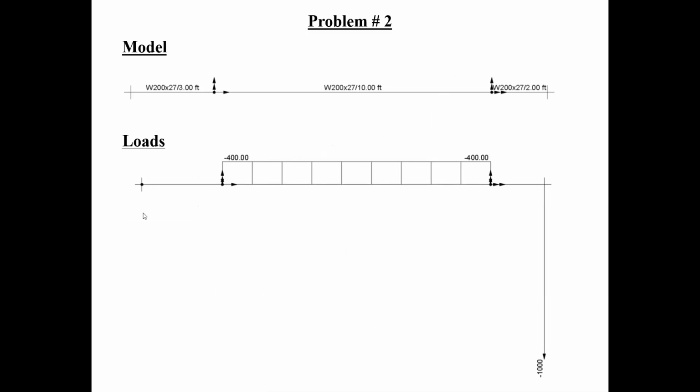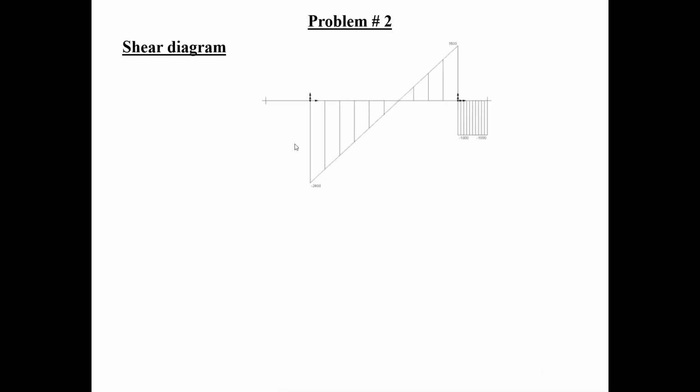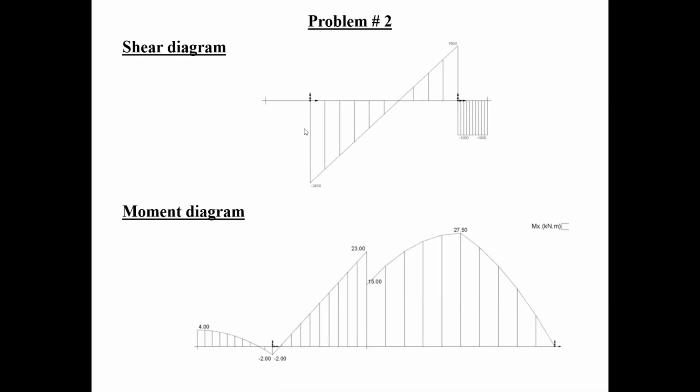I don't, because like I said, unfortunately, ADA doesn't show the moments here, which I find a little bit of a nuisance. So there was a shear diagram, and of course, the moment diagram, and there's the moment. And if I'm not mistaken, the moment was in this direction, therefore the tension is at the bottom, and therefore it's considered to be a positive moment because the tension is at the bottom. That's the way it's twisting the material.